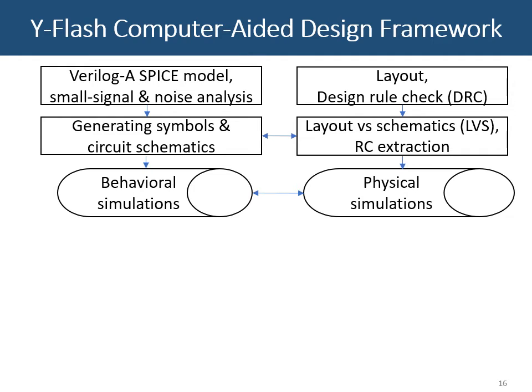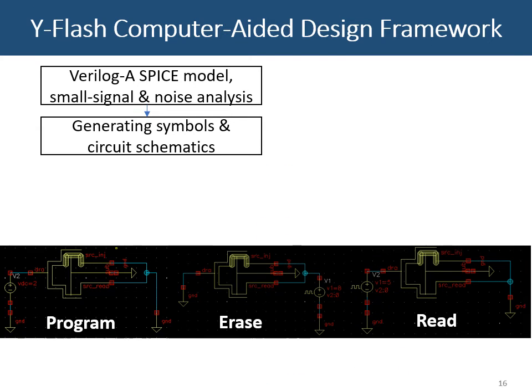After developing the deterministic and stochastic memristive model in Verilog-A SPICE model and small signal analysis, the symbols and schematics are generated, as can be seen from the figures that describe different circuitry modes, including program, erase, and read connections respectively, to be simulated in SPICE.